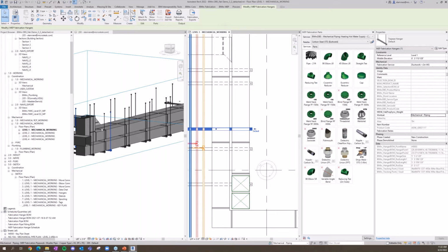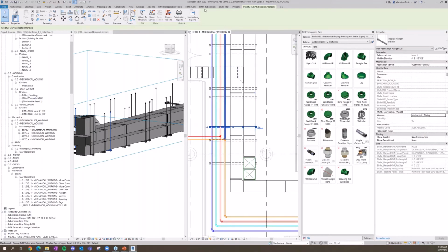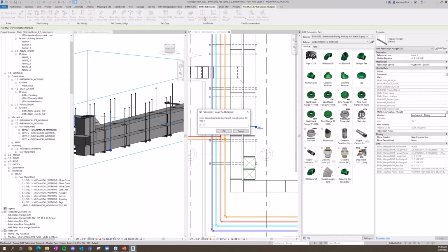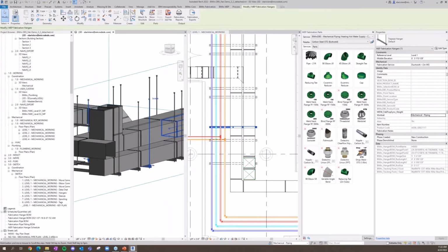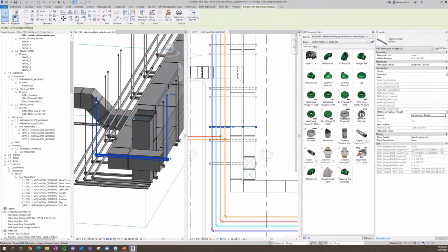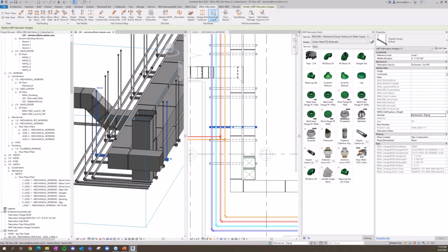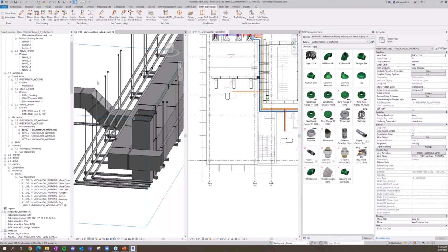And if we do decide that we want to maybe change those rod lengths for one reason or another, we can also jump in and we have a hanger rod extension. So if I go ahead and maybe give this a -6 inches here for one of those rods, I could actually treat each rod individually as well and maybe not extend the other one. And we'll see that one rod is lowered, one rod is higher. And we know it's near impossible to know which one is rod 1 and which one is rod 2. So we decided to take care of that with a nice little swap rod lengths button. So don't worry about which one's 1 or 2. Place your numbers in that you know need to exist. Swap your rod lengths to be more correct. Very, very quick process.